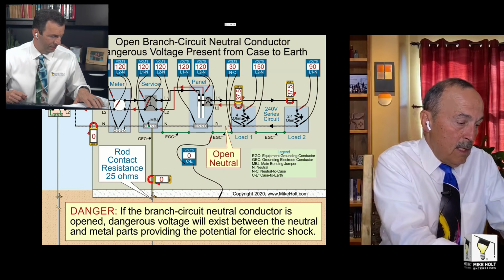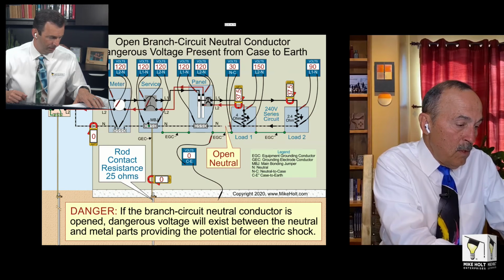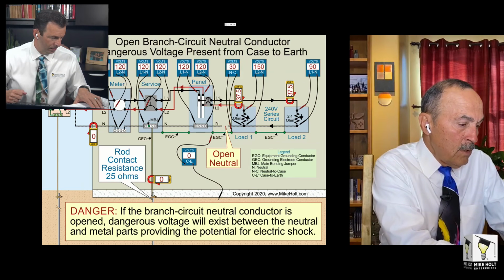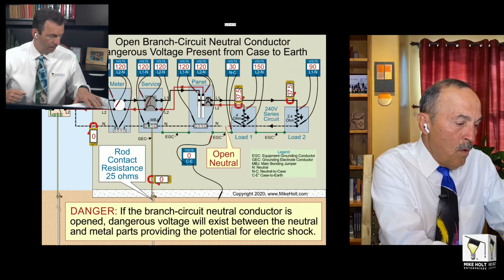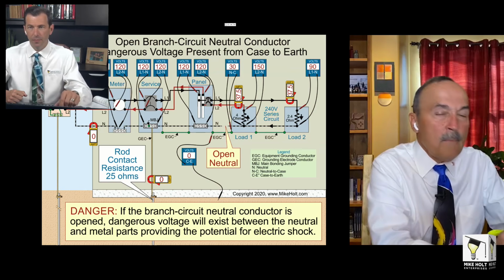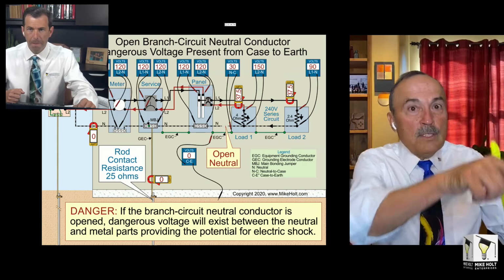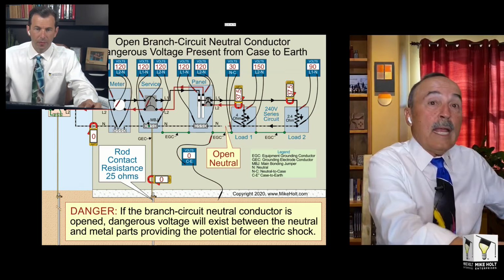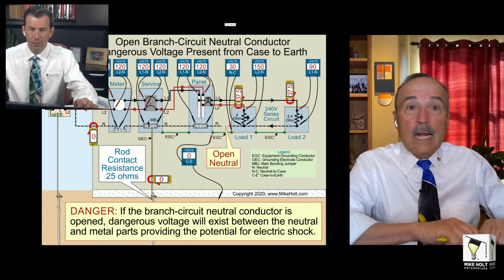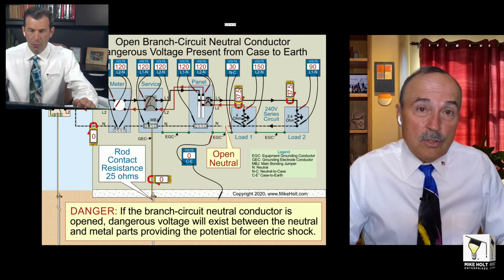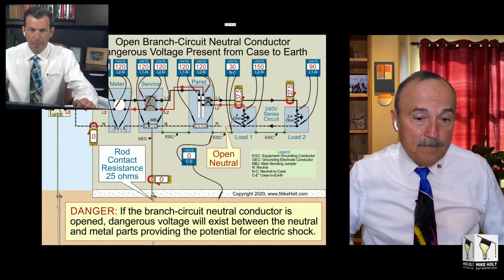Metal covers and other exposed conductive surfaces shall be bonded according to 250.92 if the conductors in the handhole are service conductors, or 250.96(A) if the conductors in the handhole are feeders or branch circuits. Okay, because I went to the wrong one, I thought that text was there, but I kept looking at D and I didn't see it there. So in a handhole, you're not required to put a terminal. You are required to connect a handhole enclosure to an equipment grounding conductor.